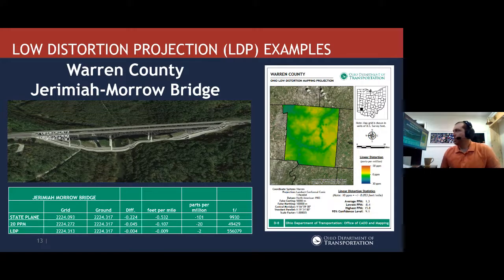Will OGRIP TIFF georeferences be adjusted? So those have a coordinate system tied to them. Even historically, they're not on the current NSRS system. They're actually on HARN, not the 2011 adjustment or the 2010 adjustment of that coordinate system. So when you do bring them in, they do reproject already, even though you don't necessarily see the changes. They do have that geo information embedded inside the file, so those files should reproject in the software.